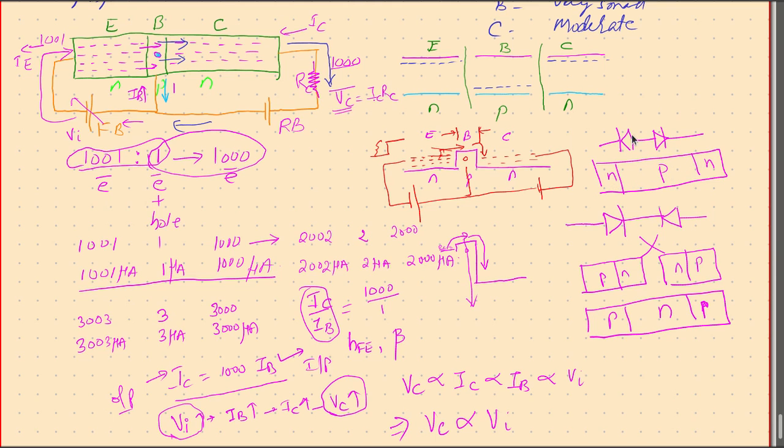That's one problem. Second problem: in a PN junction, both P and N sides are equally doped, so an equal number of electrons and holes are there on the two sides. And if you use two such diodes, you have a very large base, and therefore it doesn't behave like this. This whole wonder is created because the base is very lightly doped and this region is very small.